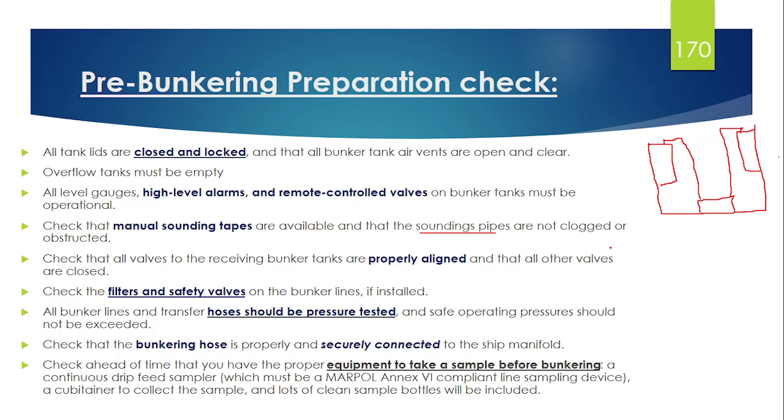One more thing I want to tell you: suppose you are starting to take bunker in one port. This is one port and this is one starboard. Now suppose you started to take bunker in the port tank. You don't take sounding of only that one tank. Whenever you start to take bunker in one tank, first you initially take sounding of that tank to ensure that you are receiving oil.